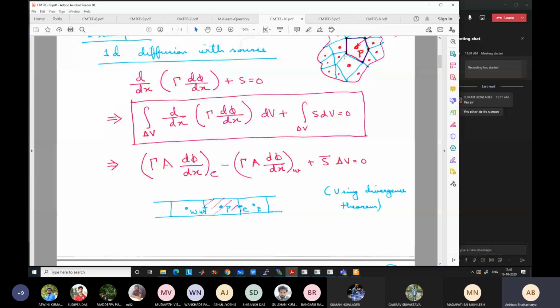If I had access to a very high-end server, it might be possible to run it in 1 week. And if it was something like a supercomputer and the code is parallelized, it may even be fast. But because that limitation is there, now they have to work with a much coarser grid. Instead of 1 million grid, they may be taking only 10,000 control volumes and 10,000 grid points. So their results will look coarse, but will still be physically correct. The results will not look good, but they will still be physical, though not give rise to a smooth solution. Is it clear?